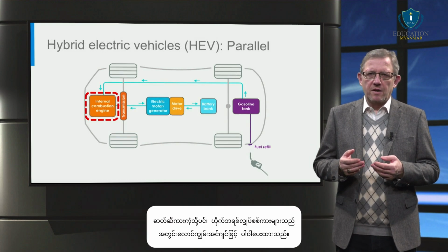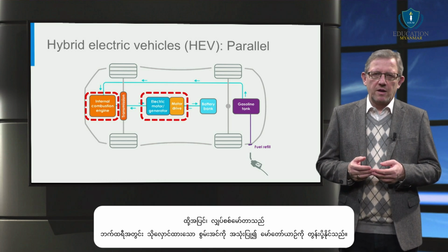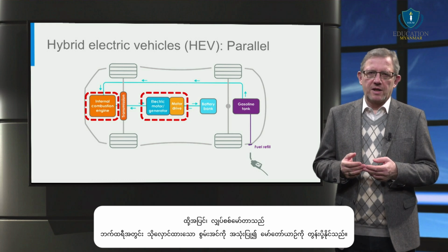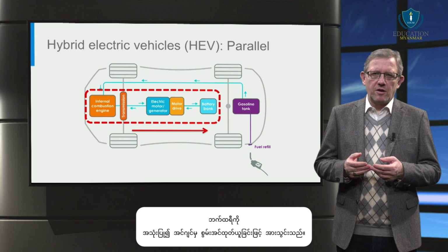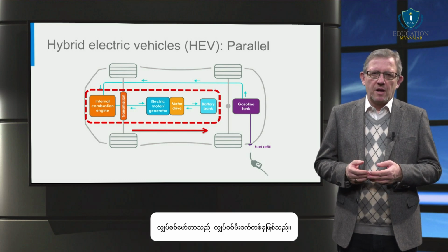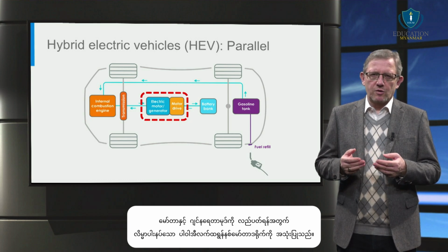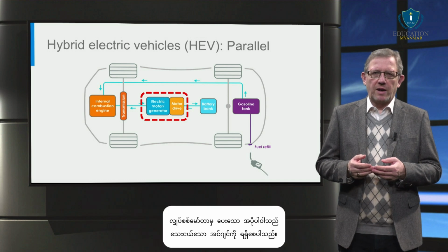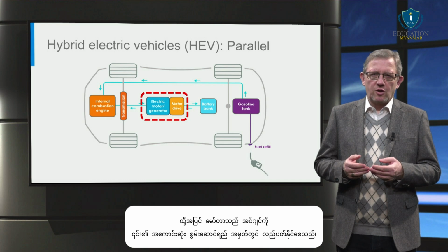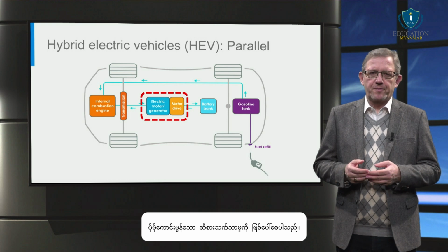Similar to a gasoline vehicle, hybrid electric vehicles are powered by an internal combustion engine as well. However, in addition, an electric motor can propel the vehicle by using energy stored in the batteries. The battery is in turn charged by drawing energy from the engine by using the electric motor as an electric generator. To operate the motor and generator mode, a clever power electronic motor drive is used. The extra power provided by the electric motor allows for a smaller engine. Further, the motor allows the engine to be operated at its optimal efficiency point, resulting in better fuel economy.